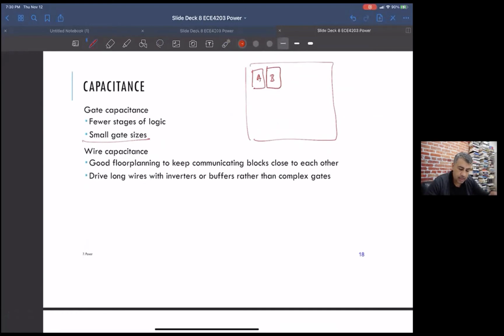Let's say you had some block, some logic path, and we went through and did a whole bunch of work on what the optimal delay of this thing is. Let's say it's some delay D from input to output. Everything we did in that whole section was to optimize the speed, to minimize the delay. But there is a trade-off between delay and energy consumed.